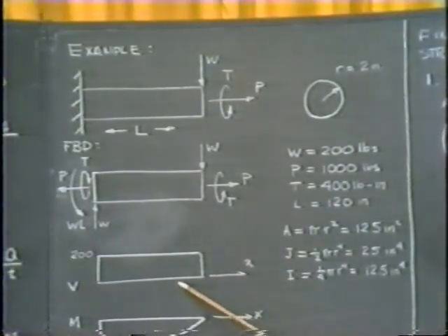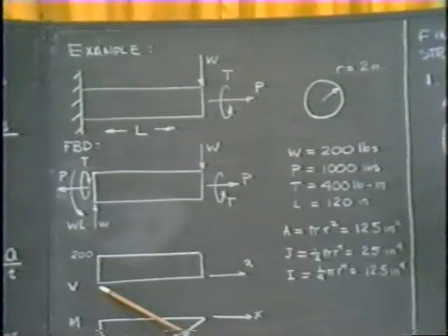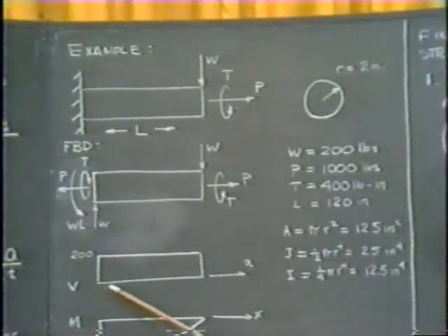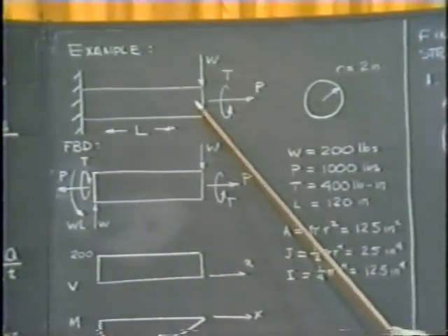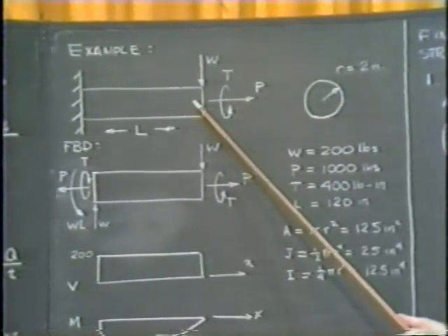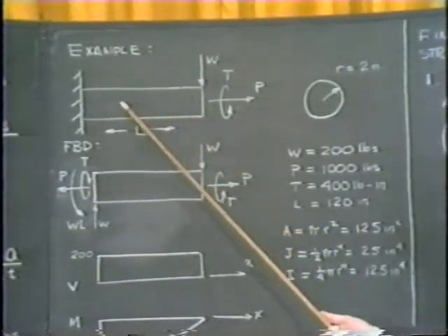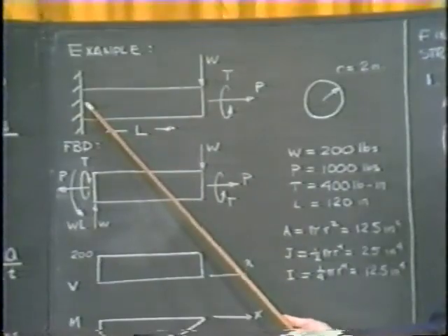The shear force is constant throughout the length, but I know that the shear stress will be a maximum through the neutral surface. So we suspect up above the maximum shear stress will occur at any length through the neutral surface of our beam up above.